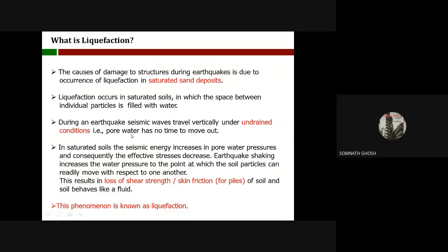Pore water has no time to move out. That you can easily understand. It's an undrained condition. So how will the pore water be able to move out, right? This is the situation. In saturated soil, the seismic energy increases the pore water pressure, and consequently, the effective stress decreases, right?